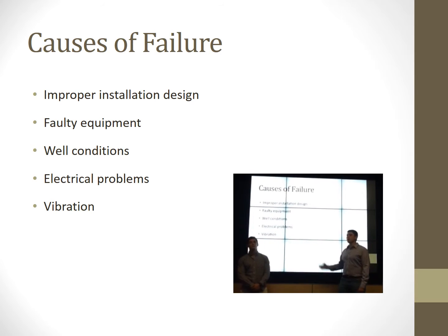The next one is faulty equipment. It's crucial to test equipment to be run downhole each time before it is run. It's especially important when an ESP is included because of the hard startups and shutdowns. Thirdly, we have well conditions. There are many detrimental effects on equipment from well conditions. These include corrosion, scale formation, sand production in the pump, high well temperatures, formation gas, and high viscosity fluids.